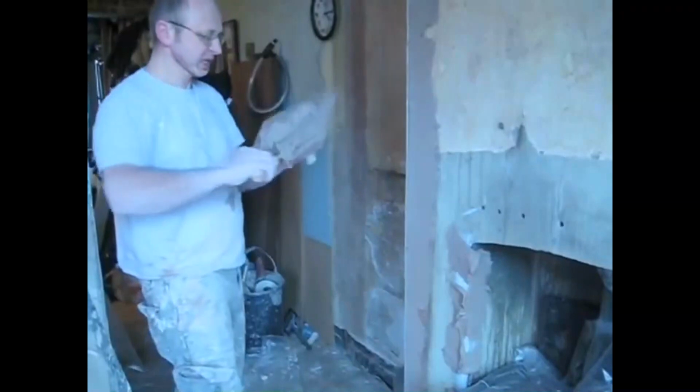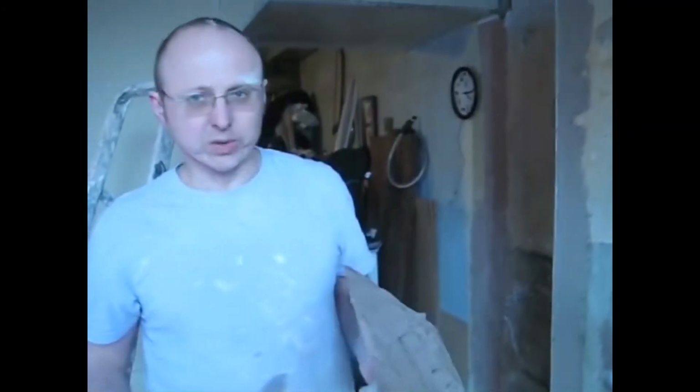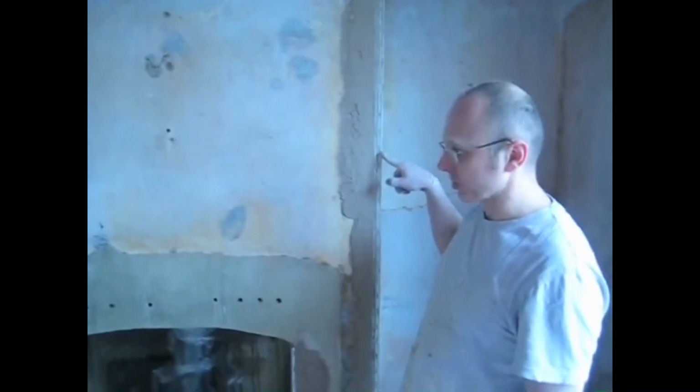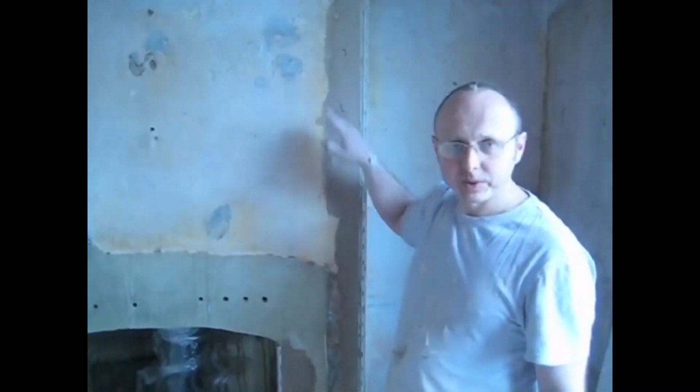A bit delayed on the ceiling, now we're doing angle beads. We're going to bond out the angle beads because they usually move, to make it a little bit more perpendicular, so when you put shelves in, they look nice. Angle beads on, put them on just before the plaster, and we're going to bond afterwards.